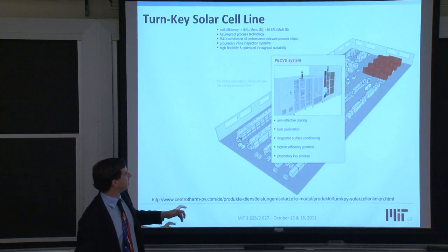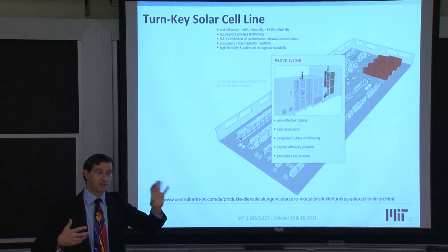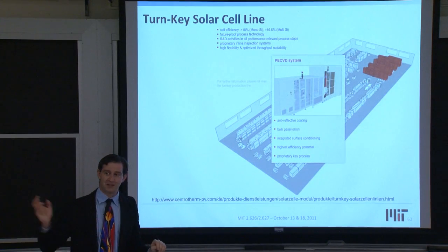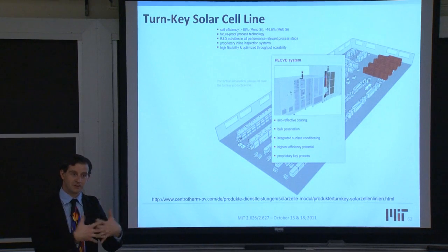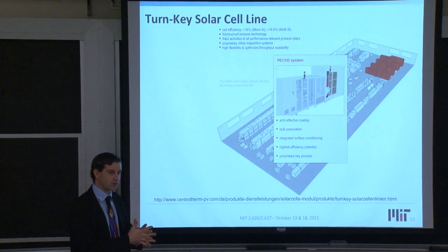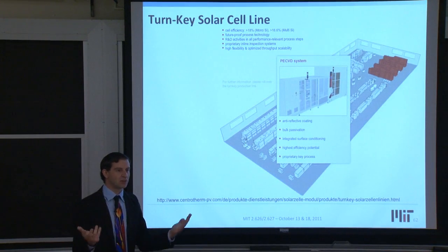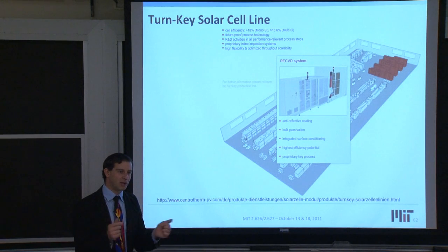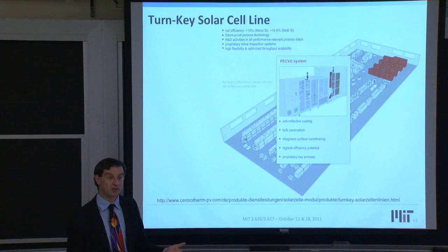And in the PECVD process, you flow in silane gas and ammonia. Silane is silicon with a bunch of hydrogens, 4 of them. And ammonia is nitrogen with a bunch of hydrogens. And the nitrogen and the silicon react on the wafer surface and create the silicon nitride coating. The hydrogens, 90% of it evaporates off, but about 10% of it hangs around, between 1 and 10%, goes into the wafer or stays at the interface there and eventually is driven into the wafer, passivating bulk defects.